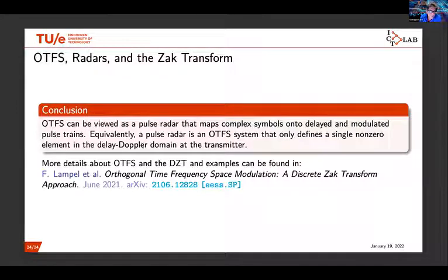Yes, but what I wanted to say here is, for example, when you talk about automotive radars, you go to 77 gigahertz because the Doppler shift scales with the carrier frequency, whereas, for example, 802.11b is below 6 gigahertz. So the parameter setting is still a bit different. Sure, so from the physical resolution perspective, they are different.